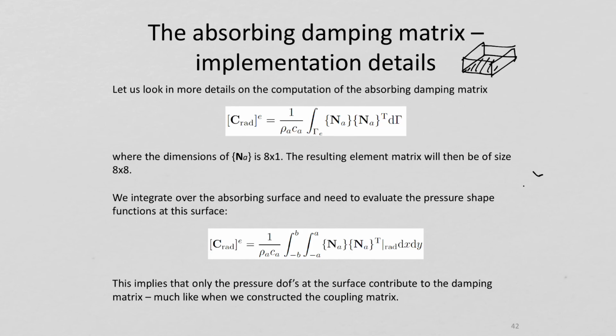Now, if we have an absorbing boundary, of course, we will have that on the top layer of acoustic elements, and at least today, for the entire top layer. We will later on do implementations where we only have boundary absorbing damping for some parts of the top. But now the absorbing layer will be the whole top here, so that represents an open cavity.